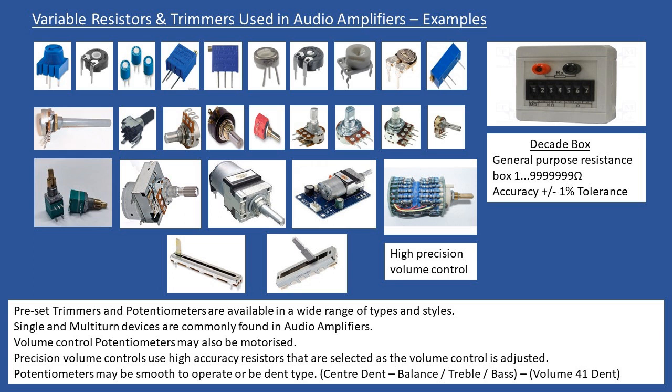So if you're repairing maybe an amplifier and a bias trimmer needs to be replaced, if you replace the trimmer and you're really at the extreme ends of the adjustment to set the bias, that will tell you that there's something else going on within that circuit that you need to look at and then rectify. And normally when you look at the service manuals, they will say, for example, set the trimmer to minimum value and then bring it up slowly, or they may say set it to approximate midpoint and then you can make the adjustment.